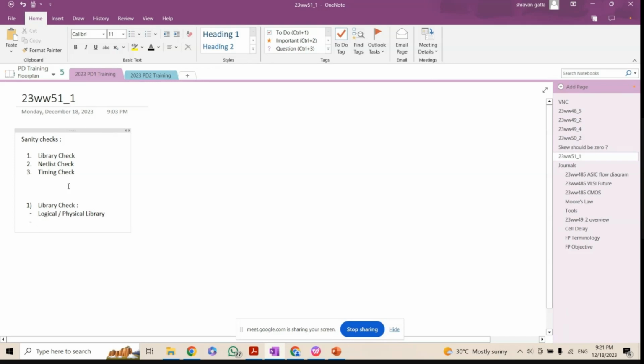So you need to fix the timing in this. I mean, your data should launch and capture within this 500 ps. Let's say this partition is A, and this is B, C. The B guy may have used 400 ps, let's just assume 400 ps. The B guy used it. How much is left for you? Just 100 ps. Okay, 100 ps only.